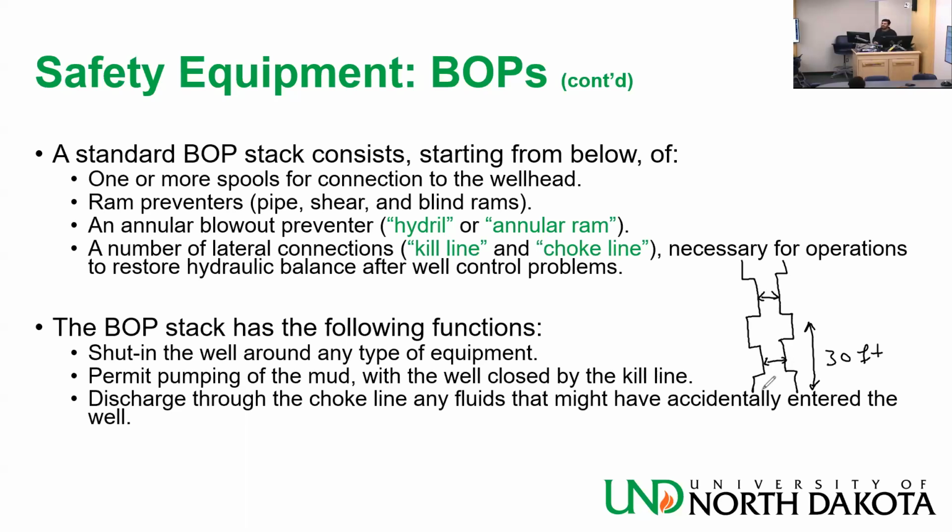Then how do I strip in? I need to open one of the pipe rams, move everything down, then close one, open the other, close the other, to get the joint through.